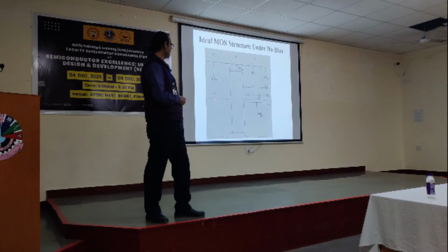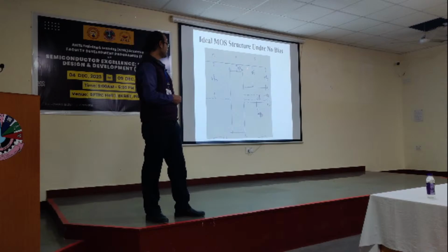And the energy required to get that electron out of the metal, this part, this one, up to the top one is called the vacuum level, right? Now, in this situation, we have assumed an ideal MOS structure. Ideal means the work function of the semiconductor and the work function of the metal are both the same. Now, what is the work function of the semiconductor?